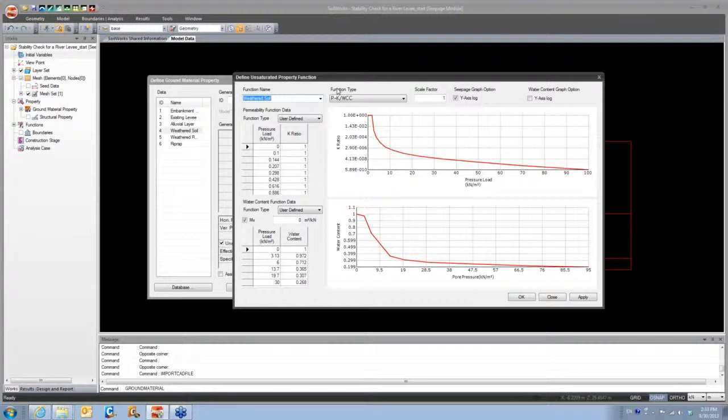Okay, excellent. So, SoilWorks is very adept at seepage analysis as well, but another great advantage that sets it apart from other programs is that in addition to doing the seepage analysis, you can also run a coupled analysis. So, for example, with this particular project, I'll show you how you can import your pore water pressure loads into your slope stability analysis to make things a lot faster and a lot easier for you.